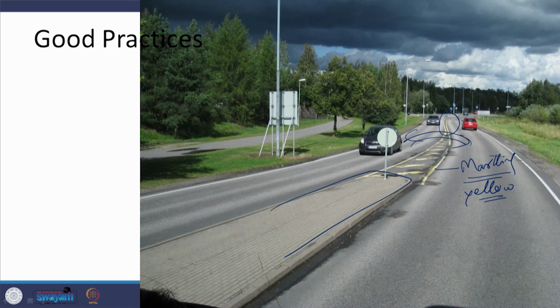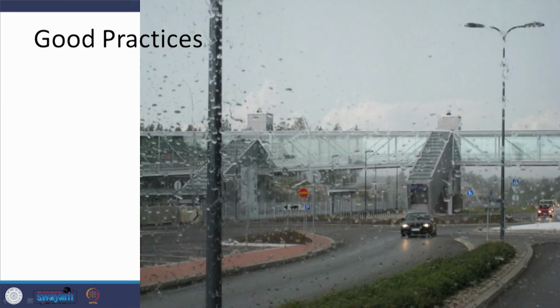And when the vehicles are coming from the direction, then it defines that you have to be on the left hand side in this particular case, or a right hand side depending on the direction of movements which we are considering. So, that is another type of design. Here also you can see that the edge marking is there along with the paved and the unpaved shoulders being provided. Here is a case where a good amount of channelization has been done at the ground level, and this channelization is helping in the segregated movements of the traffic in this particular area.